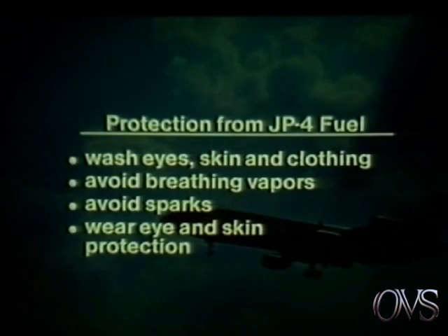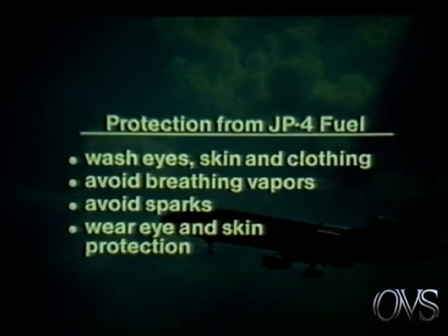How do you protect yourself from the hazards of jet fuel? If you splash jet fuel in your eyes, wash your eyes with water. If irritation persists, seek medical attention. Wash skin exposed to liquid jet fuel thoroughly with soap and water. Clothing splashed with these fuels should be washed and cleaned before it's worn a second time. If you inhale fumes from jet fuel, get fresh air. Avoid fire, sparks, and sources of ignition wherever vapors may be present or suspected. Test for combustible vapors and wear rubber gloves, a respirator, and goggles as necessary.